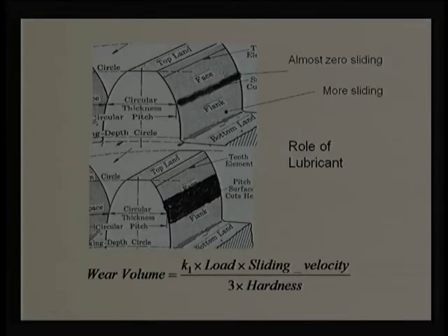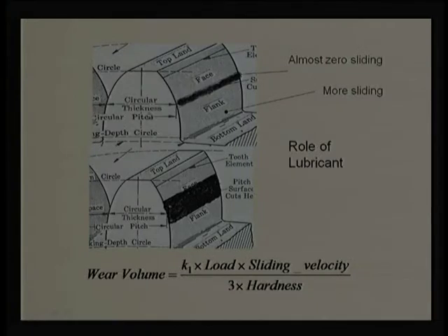And here it is also mentioned, whatever you do, as we are not going ahead with full film lubrication, even elastohydrodynamic lubrication happens only near this surface, this circle. That is why there will be some wear, and that wear can be given by sliding velocity, by normal load, by the material constant and hardness, right.